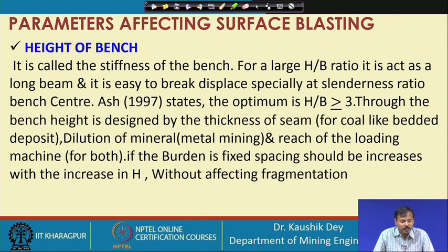Though the bench height is designed by the thickness of the seam for coal-like bedded deposits, sometimes it is dictated by the capacity of the loading equipment, or by the dilution of the mineral which is allowed over the veins, etc., in the case of metal mines. These are the parameters which restrict, or you can consider them as the constraints in deciding the bench height. But if the burden is fixed, spacing should be increased with the increase in bench height.